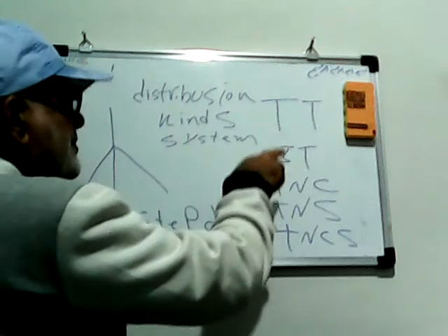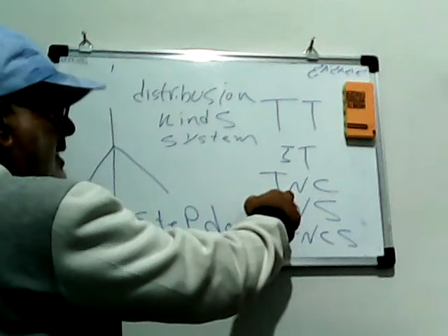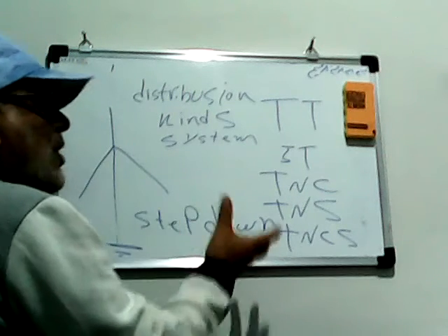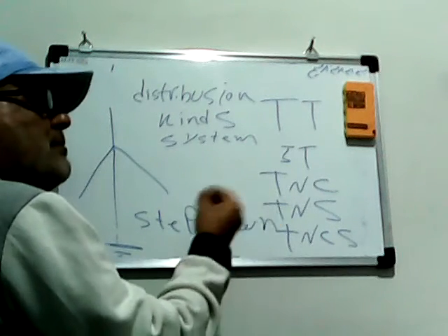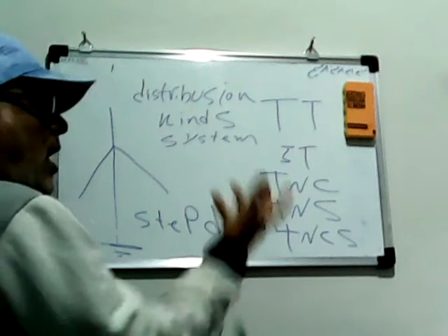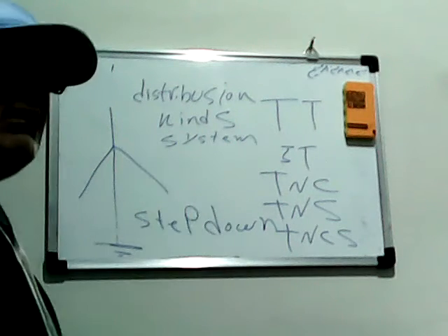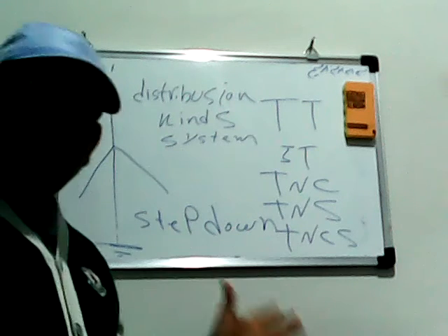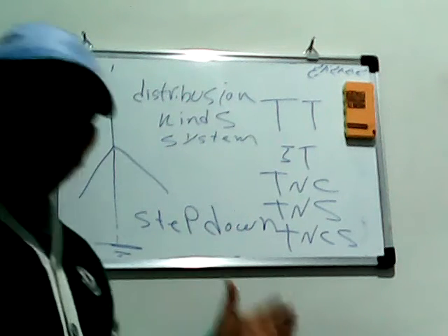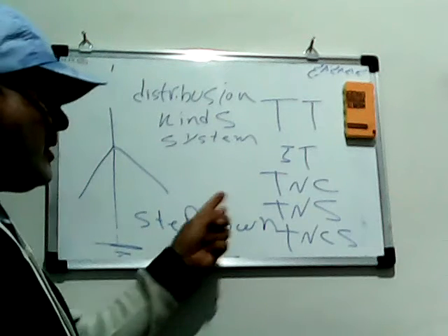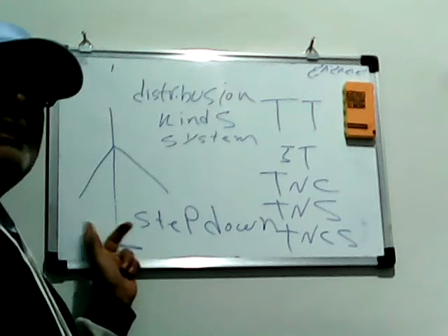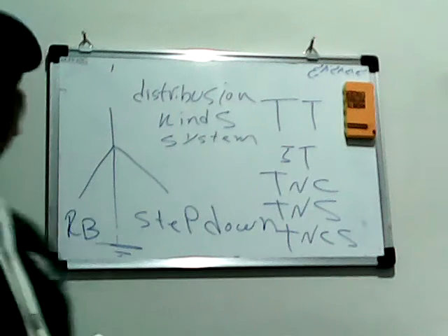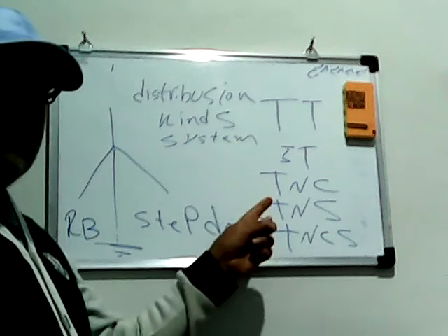Also, the second letter is N. It means we join all of the metal parts of our installation, our factories, our buildings, our refinery, to the earth electrode of the post.